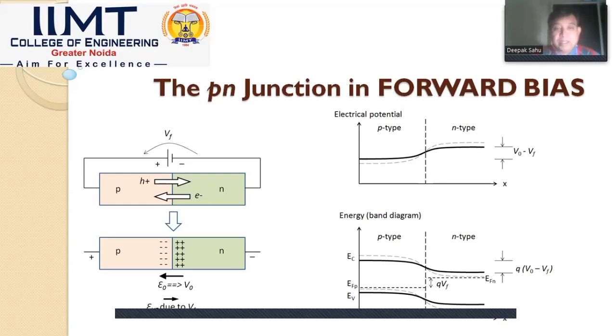So in this very elaborate system is given in which no bias and forward bias conditions are mentioned. So two movements are happening here: electrons and holes, due to diffusion, move from their opposite regions as shown by the broader arrow here, and H plus and E minus. And additionally the external applied field forces the holes and electrons to also cross the region.